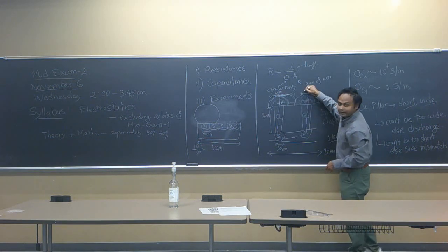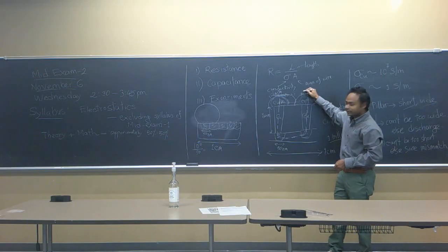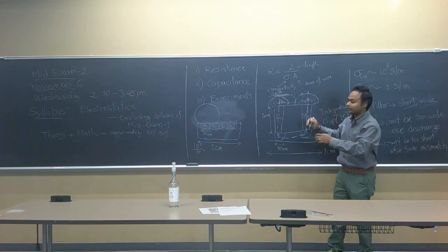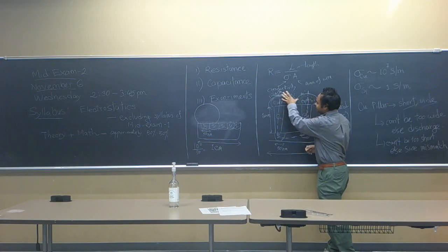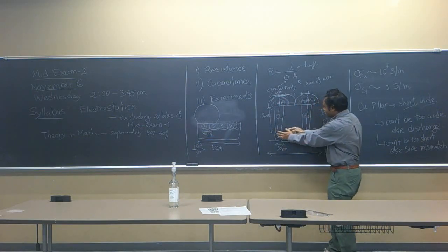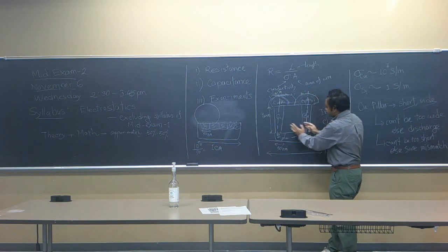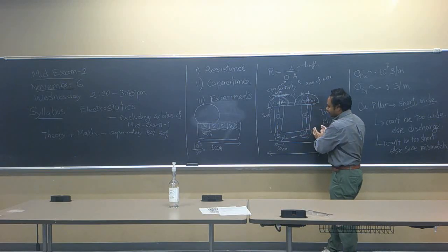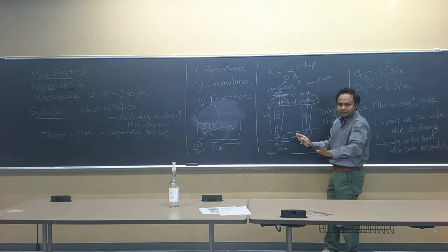Then there is no point of applying any voltage. The silicon devices underneath will not see the voltage. The current will just go through, right? So this is why, if you have just one device, you can connect with the copper bump. But if you have many devices, you cannot put all these big copper bumps on each of these individual silicon devices while also keeping them isolated from each other. Does it answer your question?